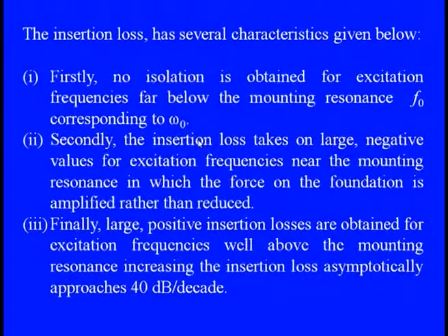First, when no isolation is obtained for any exciting frequency, the exciting frequencies are always far below the mounting resonances. So, this F0, the exciting frequency, is always far lower than the mounting resonance.